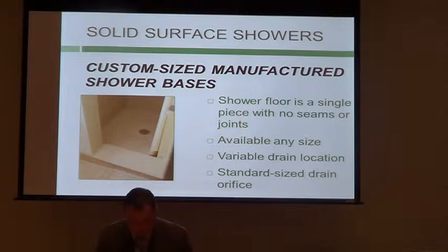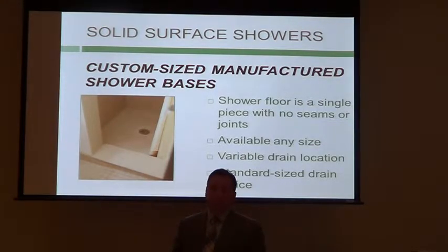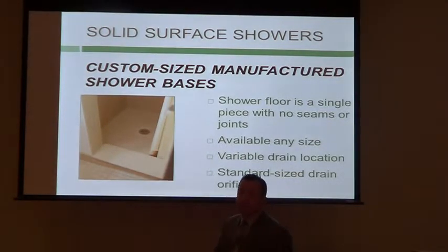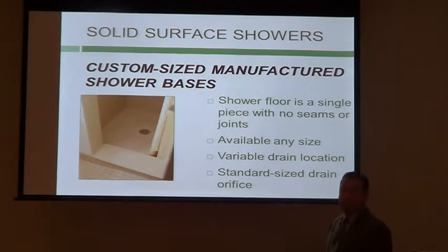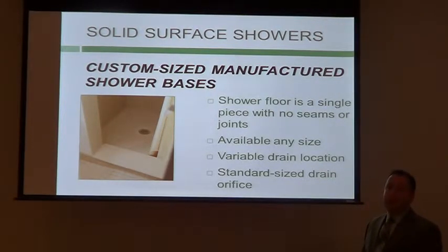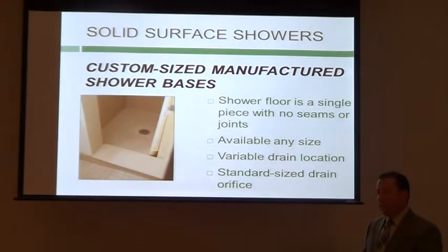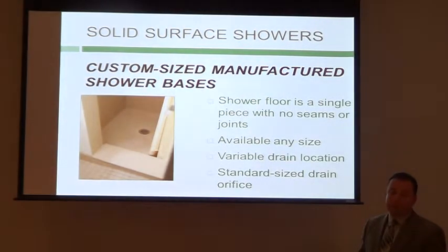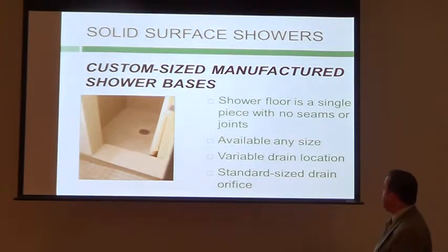And this is just a small little area. At the minimum at the drain here, I'm at about 5/8. So what is that? Maybe a foot? At a foot, I'm already climbing up to, let's just call it, a nominal 1 inch. Strength and durability of this pancake like nothing else. The load test on these is 2,500 pounds or greater. So it's a phenomenal application when you want strength and durability in a commercial setting. And we're seeing a lot of uptick in the bariatric units because they need that strength built into the floor.